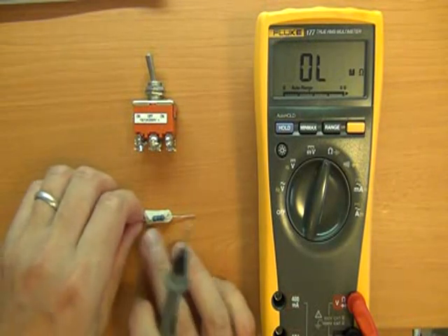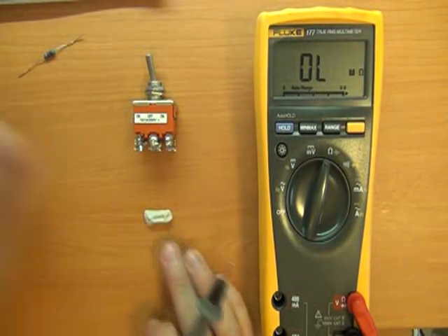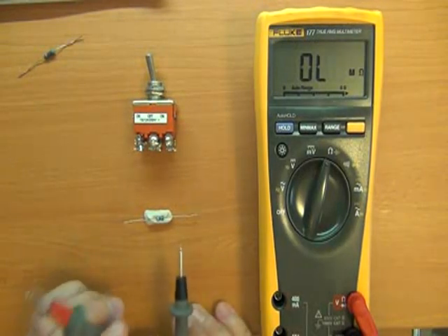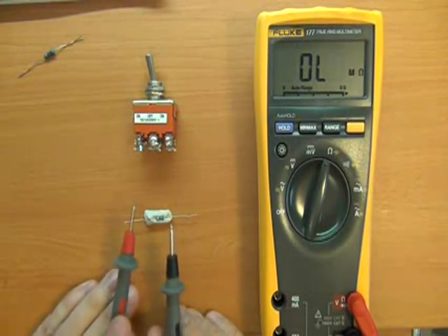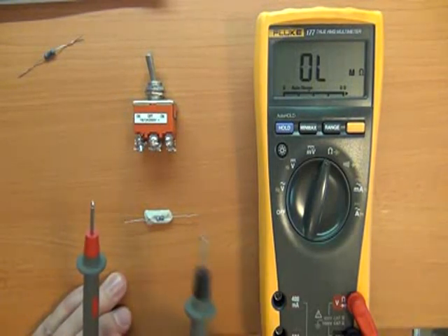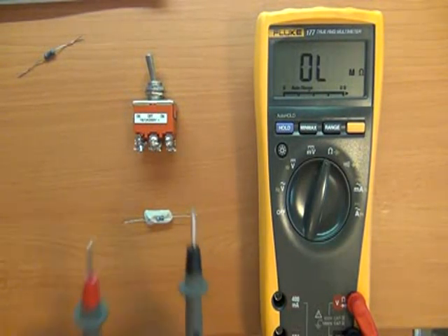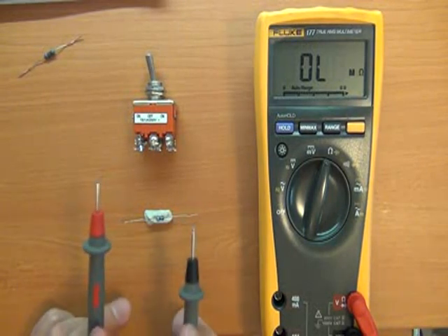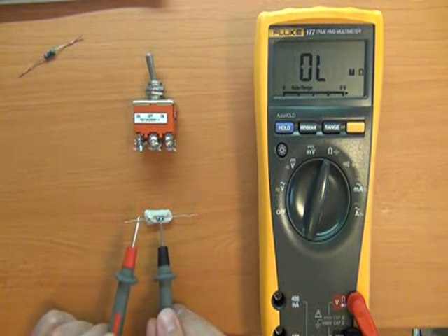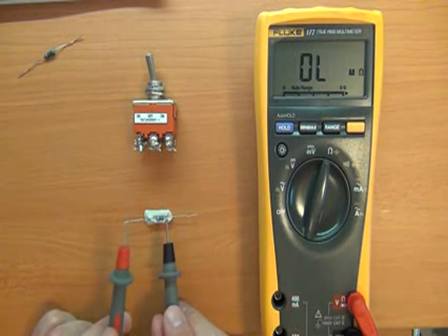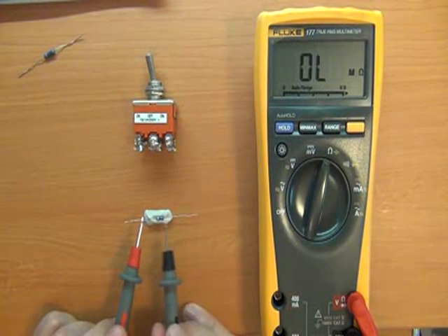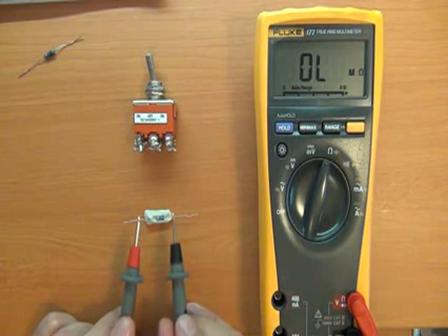Now let's get another resistor. Again, you'll note this is out of circuit, because if you're trying to find resistance in a circuit, you're measuring the resistance between all the components between your two probes. If you want to measure something specifically, sometimes you have to be very careful. You have to take it out of the circuit to get a good clean reading, or else you could have other components within the circuit which could upset your reading.